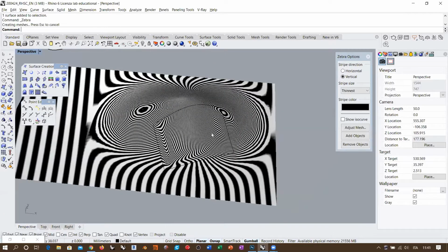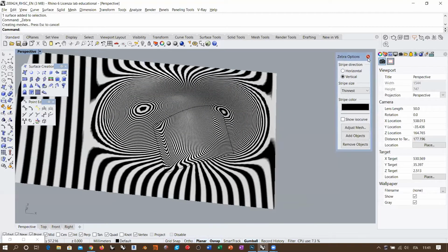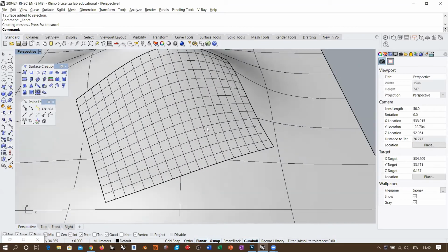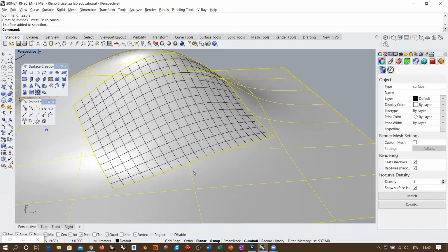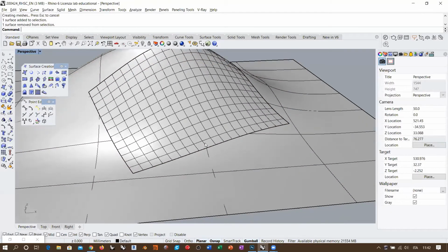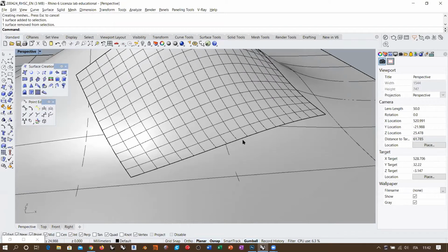In general, the problem here is that what the command tries to do is, if you select curvature continuity along one edge of the network surface, the surface will be deformed in order to have the first 2 lines of control points properly set and adjusted in order to be continuous with the surface on the other side of the edge. But this is something that can easily be achieved along the edges.